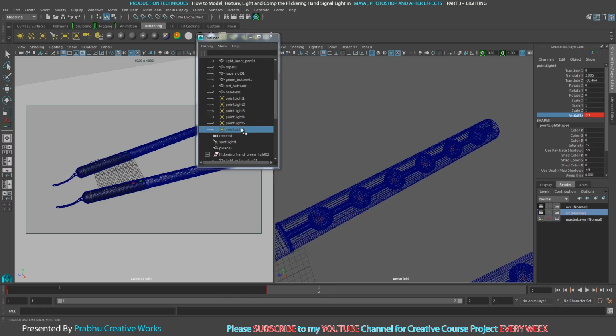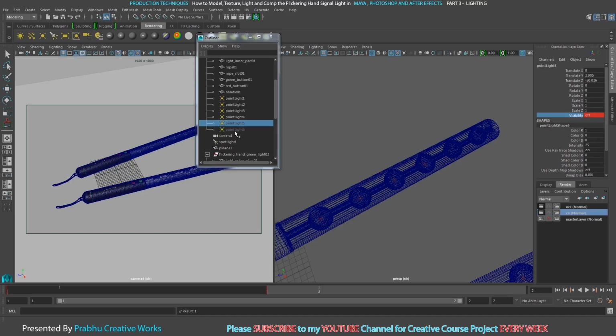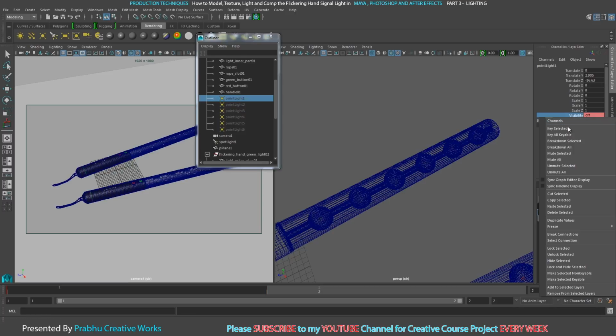So select this second frame, select the point light 5, select over here, press 0 and press enter, right click and choose key selected. So you want to do the same thing for here also. Select this one, 0, enter, right click and choose key selected. Select this one, 0, enter, right click and choose key selected, select this one, press 0, enter, right click and choose key selected.